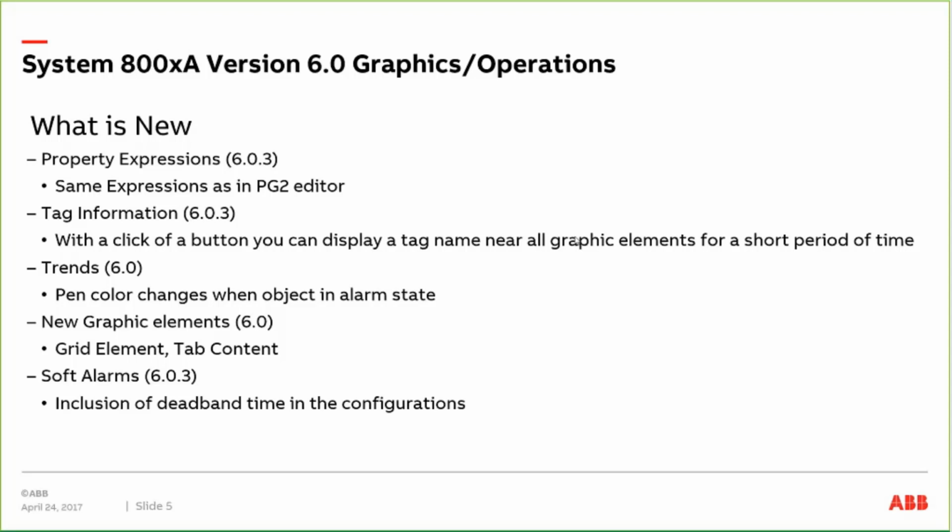So the verb button in this situation I used it for was to start that Windows application. Normally, if it's just a pure aspect, if you can see the view inside of 800XA, then you use an aspect. The verb is more for if it's going to do something outside of 800XA. In this case, to open up Excel, or open up PowerPoint, or open up a PDF, or even open up Windows Calculator.